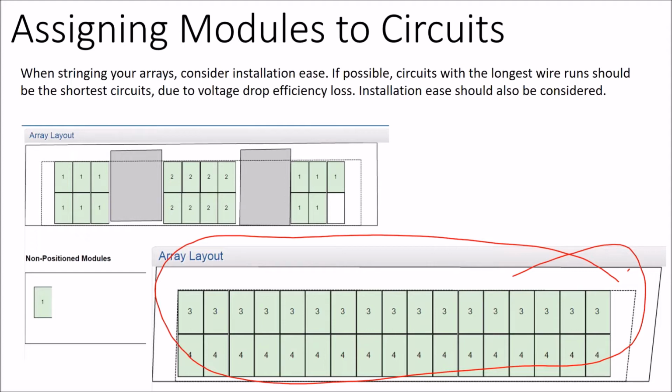And there's a few different ways to do this. Remember with a string inverter, you have 12 modules per circuit and 2 or 3 circuits. And all the circuits have to have the same number of modules on them for each power point tracking device, which the inverter nowadays may have 2 or 3 power point trackers. That didn't used to be the case.